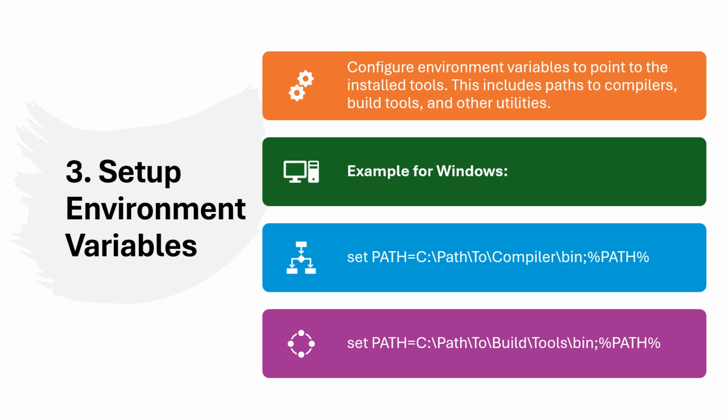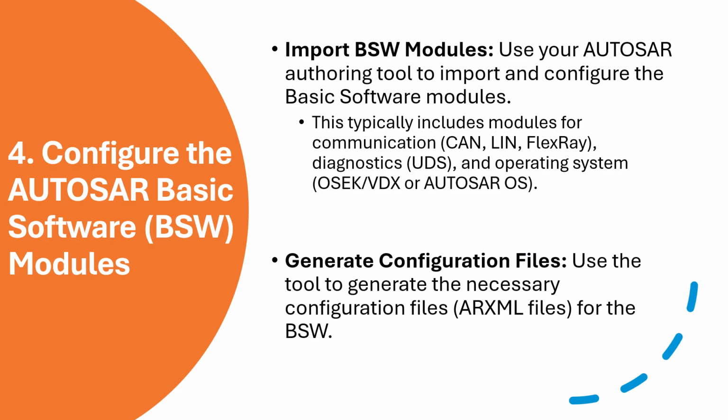So the next would be to configure the AUTOSAR BSW modules. This will be the main part. The next step is configuring the AUTOSAR basic software modules. The first is you need to import the BSW modules. Use the AUTOSAR authoring tool to import and configure the BSW modules.